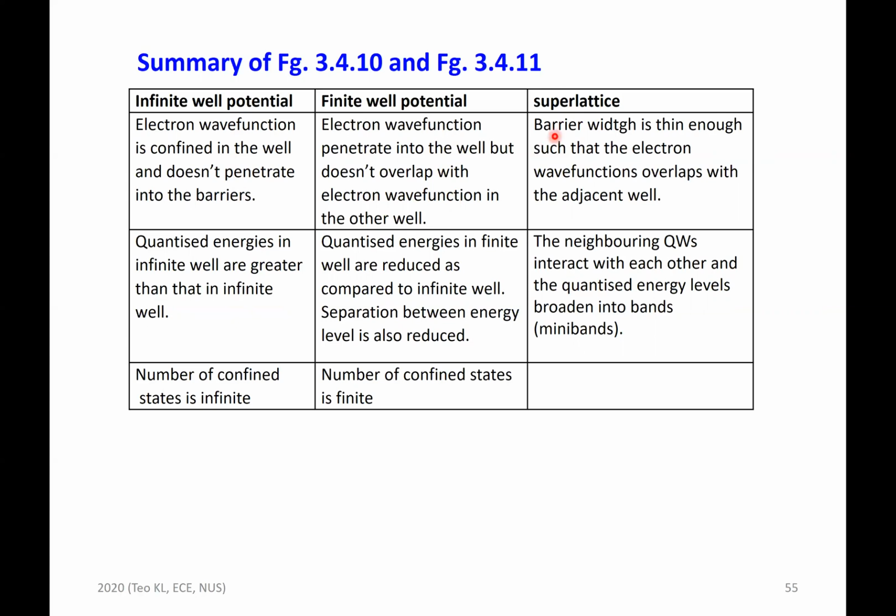Now for a superlattice, the barrier width is thin enough such that the electron wave function overlaps with the adjacent well. There's a wrong spelling here, it should be WIDTH, that's the width. Now in the infinite well potential, the quantized energy is greater than the finite well. I think there's a mistake here. It should be greater than that in the finite well.